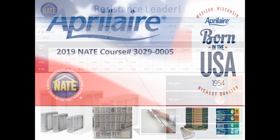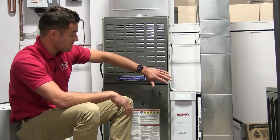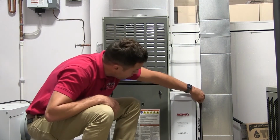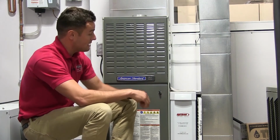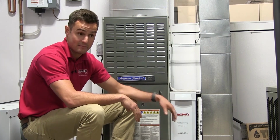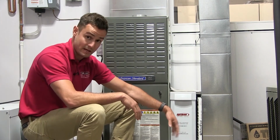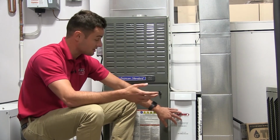Let's watch another video here. So one of the things that we use this particular demonstration and setup for in our training room is to show our technicians, really to make them believe, this is the difference in the static pressure drop between your standard 1-inch filter here and your media cabinet. So we can actually take one or the other out and measure the static pressure differences across the 1-inch versus our 4-inch media cabinet to really get our technicians to say, wow. And you can actually hear the difference in the fan when you have the 4-inch media in versus the 1-inch media. So it really builds belief in our technicians that this is good for our customers.